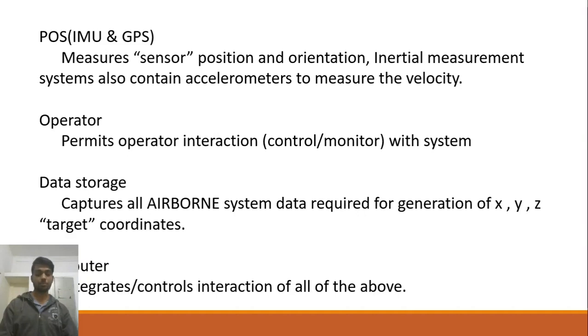Data is required to process and return the time for each pulse scattered back to the sensor and calculate the variable distances from the sensor or changes in the land cover surfaces. After the survey, the data are downloaded and processed using specially designed computer software. The final output is accurate, geographically registered longitude, latitude, and elevation for every data point.